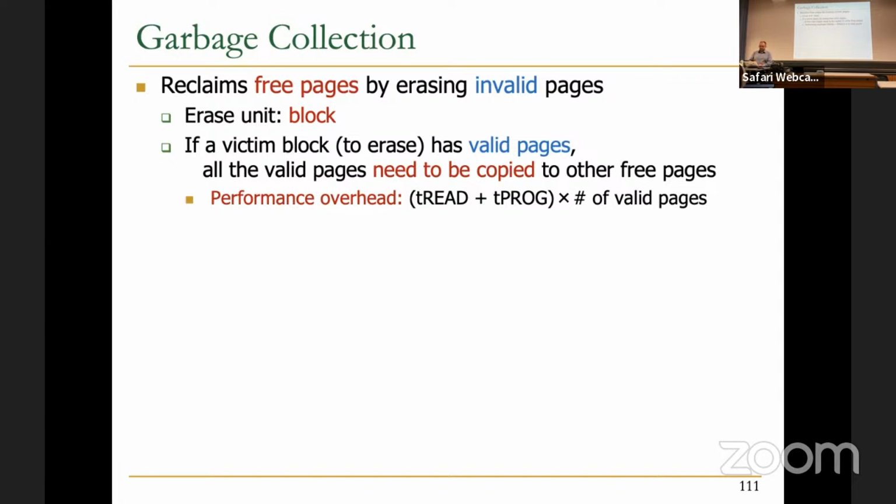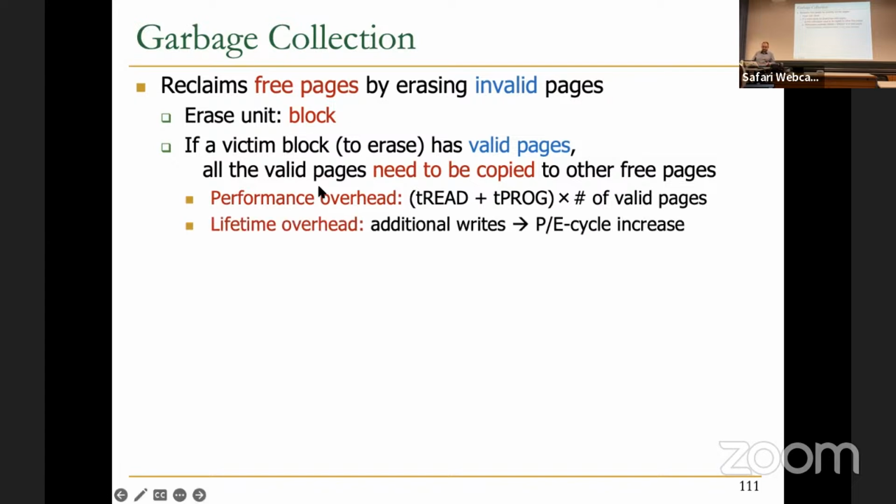So you have T read plus T program times the number of valid pages. It also has lifetime overhead, so you have additional writes, which can cause program erase cycles to increase. This is known as write amplification. It is a known metric for SSDs that people report.